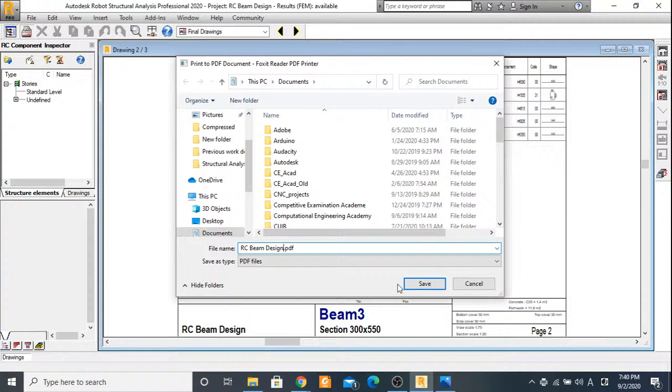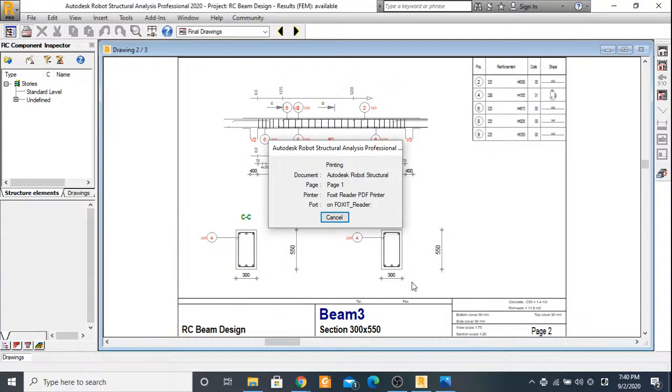Or as many times it is the case, you may want to have this drawing in a setting where you can actually edit the drawing, all right, to be able to suit what you have in the field. But what you have here is already a good working vantage point, right? Now you can elongate some bars and all the like to make it more feasible and more realizable in the field. But make sure that you never reduce the amount of steel area in a particular cross section. You may rather want to increase, but maybe not reduce, and not increase to the point that the beam is over reinforced.